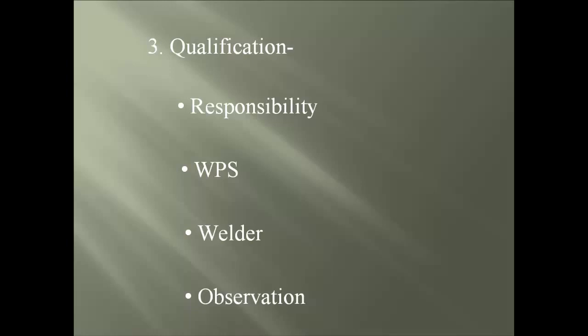Notification in advance of any production work. Base metal is checked for compliance. Verifying of the approved WPS and welders. Welding equipment are in compliance. Working conditions are safe. Weld assembly size, length, and location conform to drawings and codes. The technique and performance comply with the WPS and code. And lastly, any identifying marks shall be located and recorded on each weld assembly.